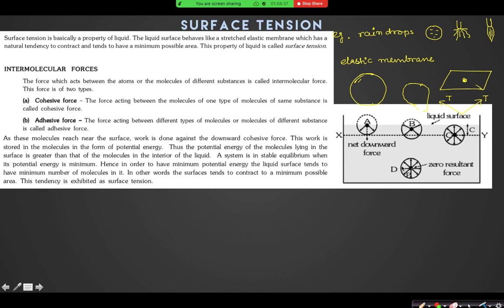And why am I talking about only this small sphere? Because the cohesive force or adhesive force is only applicable for a very short range. So only the nearby particles will apply a cohesive force to this central fluid particle. As the particle is symmetrically bounded from all directions, the net resultant cohesive force on this particle is zero.